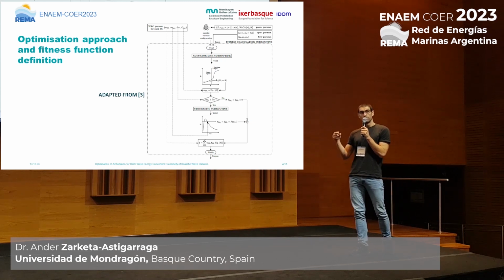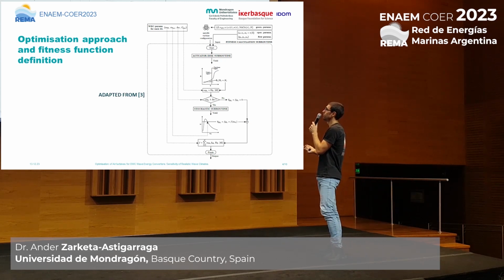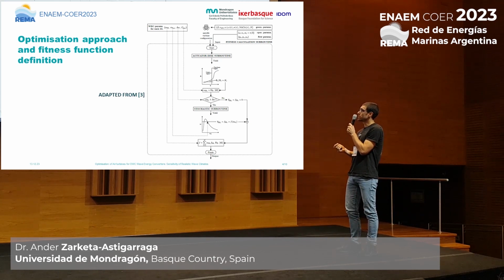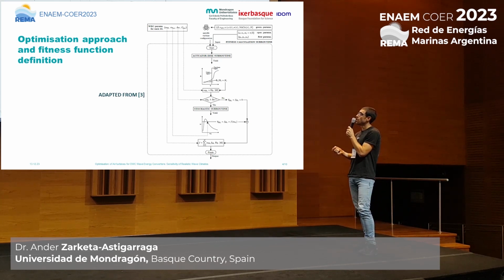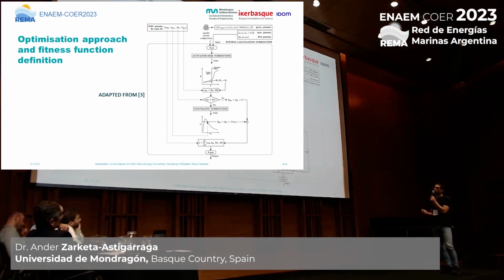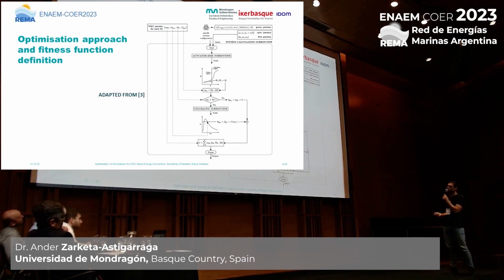If it doesn't, and if it falls within the pre-established interval of accepted rotational speeds, we proceed by calculating the stochastic curves, and we enter into the efficiency curve with the dimensionless standard deviation on pressure. We read the corresponding stochastic efficiency, and we repeat that iteratively for each C state. At the end of the day, the score or the fitness we have is a kind of a weighted sum of such stochastic efficiencies with some weights, and those weights are represented by the probabilities of the C states. Okay? So this will be the optimization strategy.